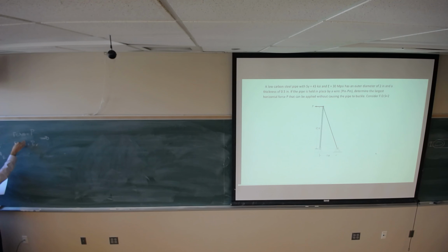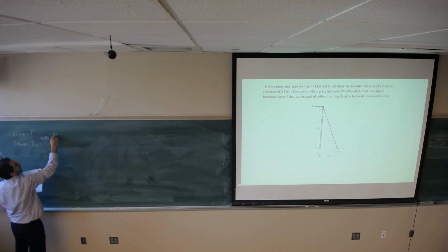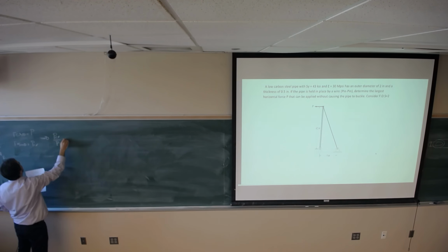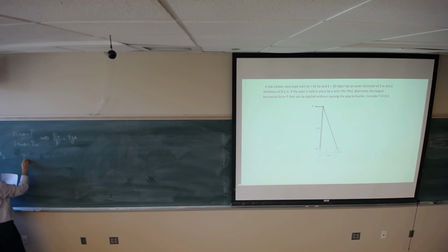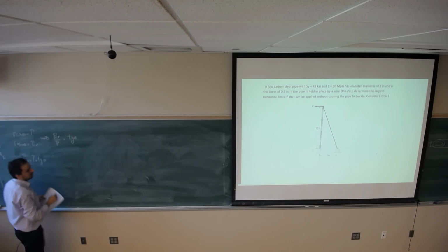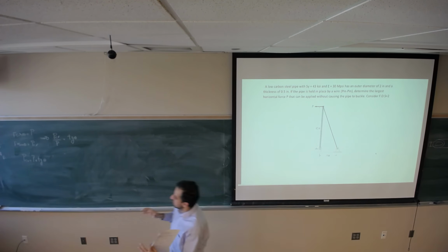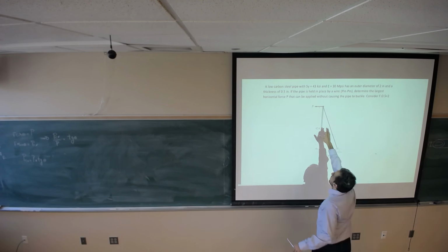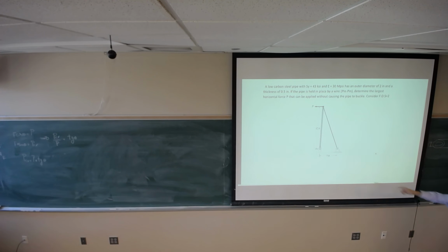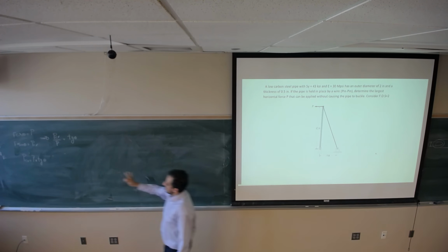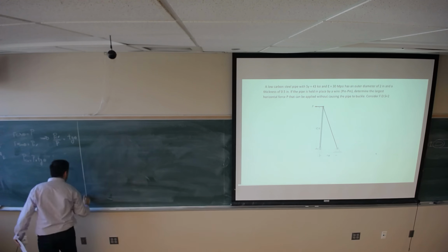Dividing this by this, it's going to be P critical over P, which is the tangent of theta. So P critical is going to be P times the tangent of theta. This is how I find the relation between P and the force applied to the pipe. Now I'll stop here and go to the buckling analysis.